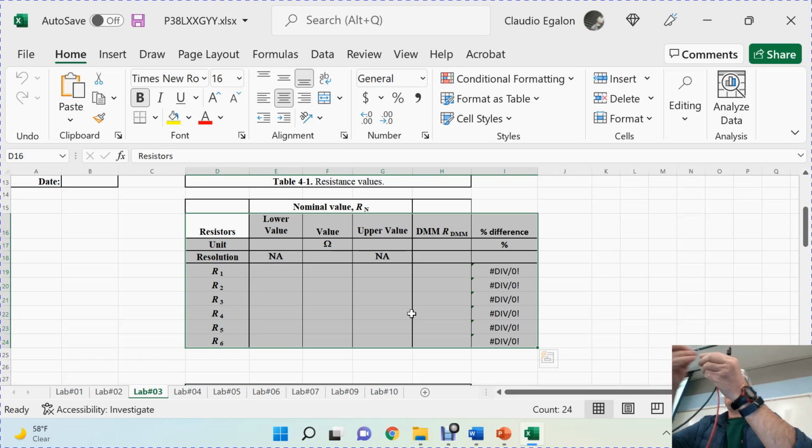All you have to do is clamp the ends of your resistor to measure its resistance. Make sure you use the most sensitive scale of your multimeter, okay? That's what you do. Keep track. You're going to measure the resistance in two different ways, okay?